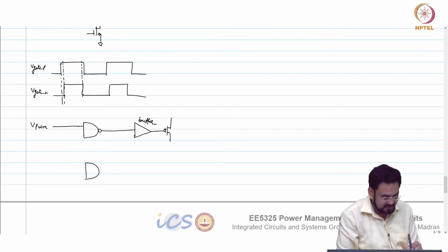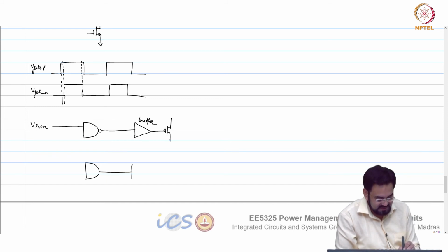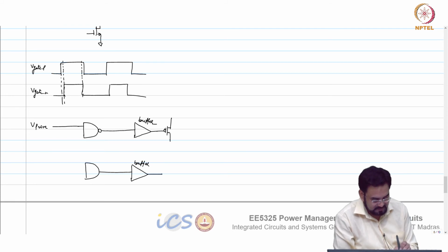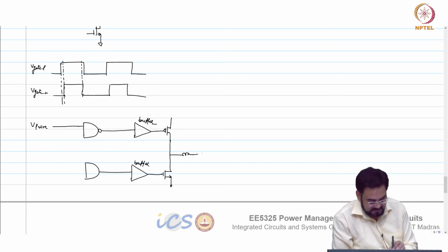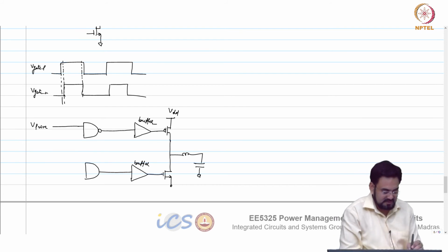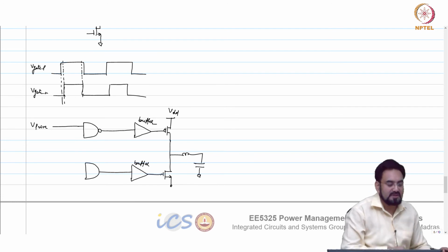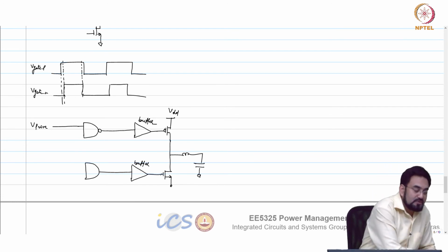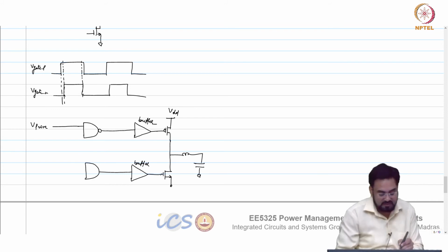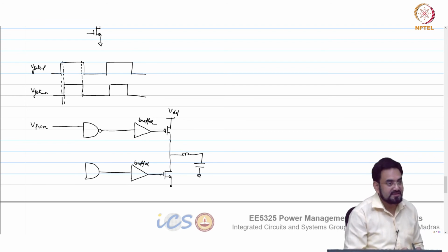And then on the other side, this is your buffer again. You have NMOS and they are connected together. This is where you connect your LC. And we want the gate of this NMOS to go to 0 when VPWM is high. So when it is high, I want to make it forcefully 0.